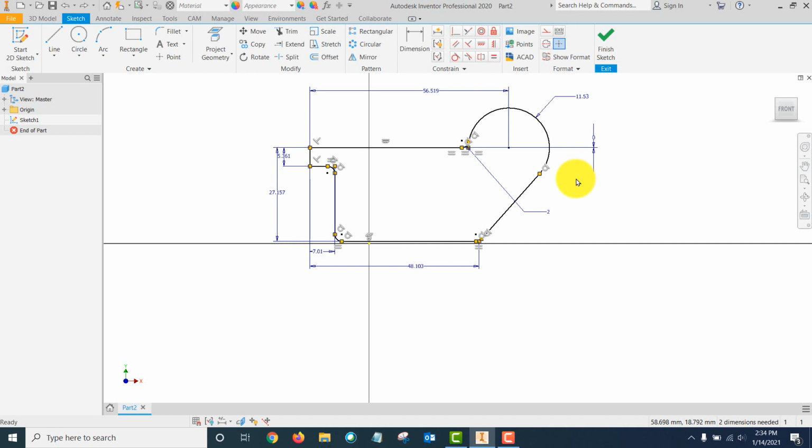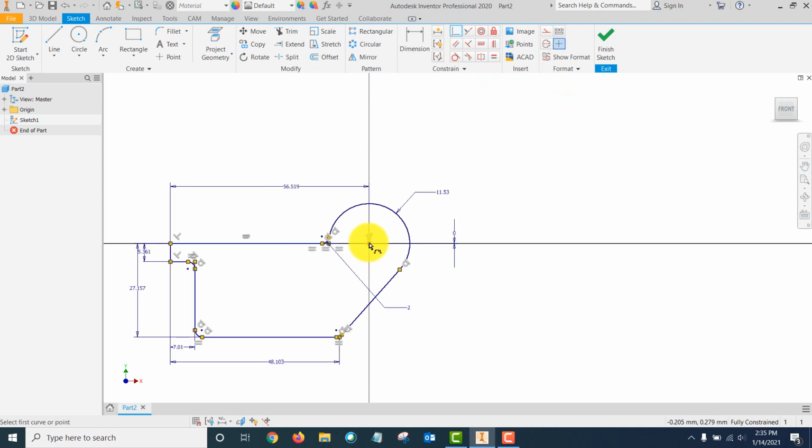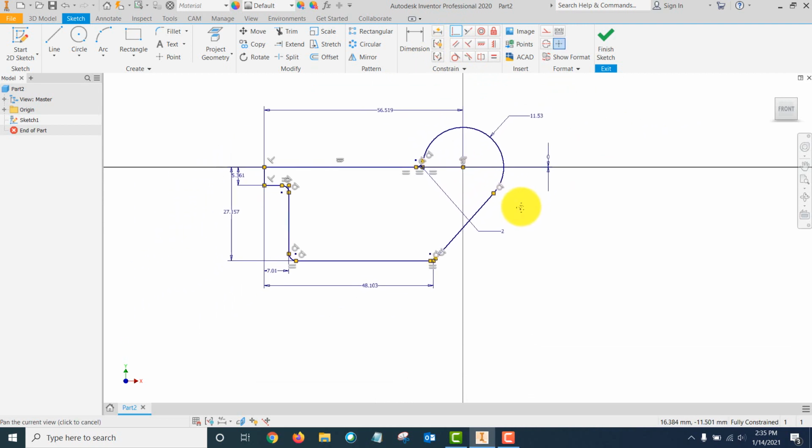So that works. The problem being is when you start assembling parts together into an assembly, you can use the XYZ planes as mating surfaces. So you can mate the plane of one part with the plane of another part, and they line things up. So I really like keeping things aligned with my planes in some way or another. So I am going to do a coincident constraint for the center of my circle to the origin, even though it moved things around a bit there.